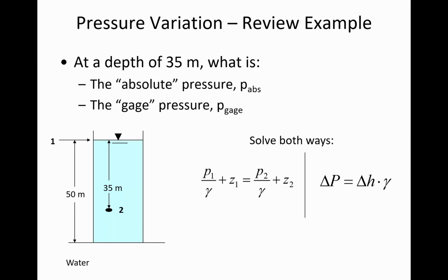Now, there is some symbology here and a convention that I need to address. It's typical in fluid mechanics texts for this triangle on top of the water. You can see the triangle there. It kind of indicates that it's in contact with the atmosphere. And so that's a clue that this tank isn't sealed, but rather it's vented just to whatever pressure is existing at the air above that.